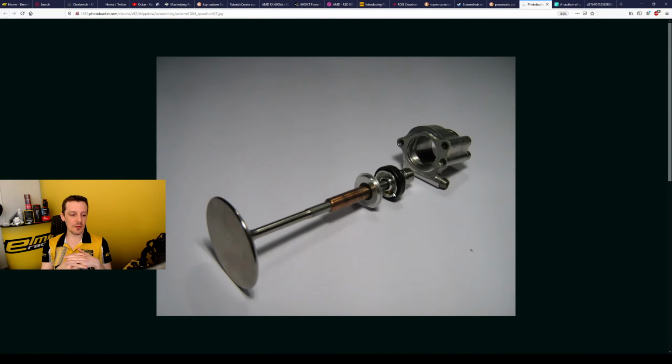But for F1 engines that do use pneumatic valves, of course, you just hook up a pressure source and pressurize those, and then you can have all the valves on the cam lobes before you start up the engine. So that's not really a problem. And I think you could maybe do that with street cars also, especially with the current high capacity batteries, and especially with things that have some kind of mild hybrid system.